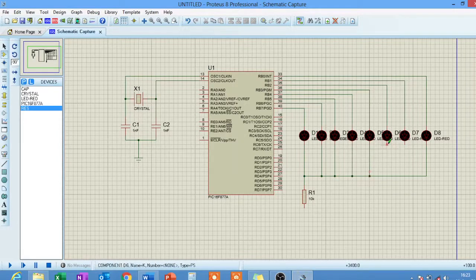After all, only one LED will be on at a time, so we are not worried about the total current, because we'll have only a single current flowing at a time through the resistor. That's why we can conveniently use a single resistor. So we can connect this, because this has to go to ground now. Also take note of the orientation of my LEDs. I connect them such that the cathode points down, which is going to be my ground, so that is forward biased. Just take note of that.